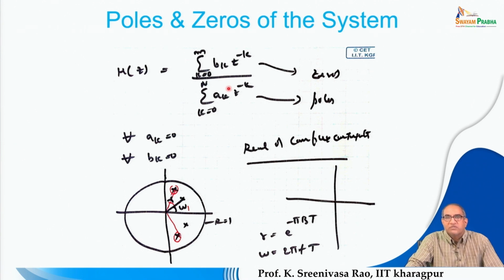In the case of nasals, we have both poles and zeros, and in the case of vowels, where the vocal tract is completely open, the system is very much dominated by complete resonances, and there are no anti-resonances. That means there is no energy trapped inside the oral cavity. Therefore, the system can be approximated as an all-pole system. And most of the sound units are produced by the dominant resonances.